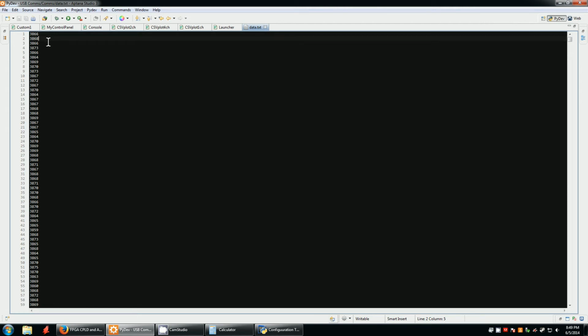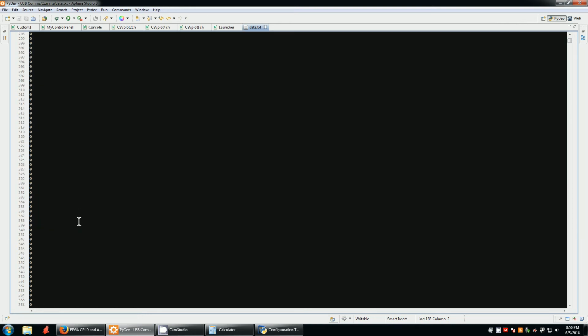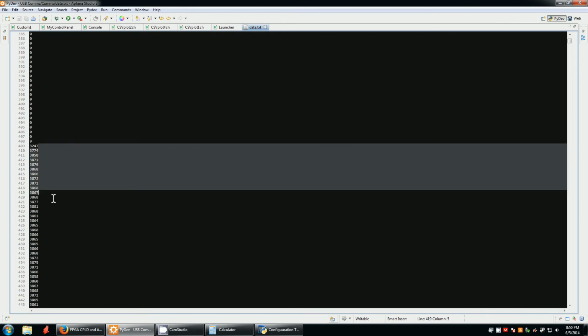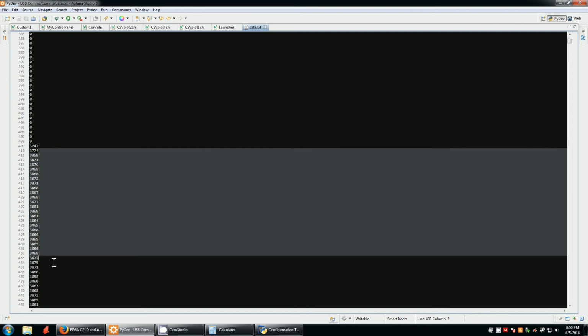So if this rectangular square wave was 0 to 3.3 exactly, we'd have 4096, but it's a little low, so we get 3860 and change, 3880, and so you can see a transition here, falling edge. Now it's at 0, and it'll transition back to a rising edge. You can see you just catch the very bottom of it, and then it goes back up to just below the peak, and then we're back up to normal.